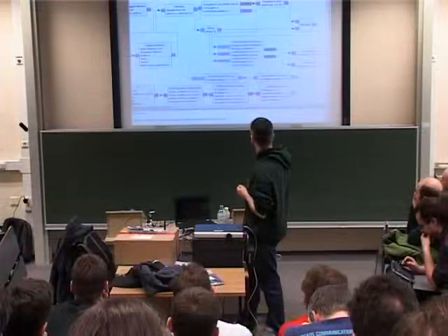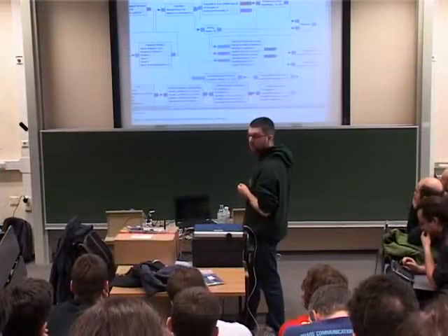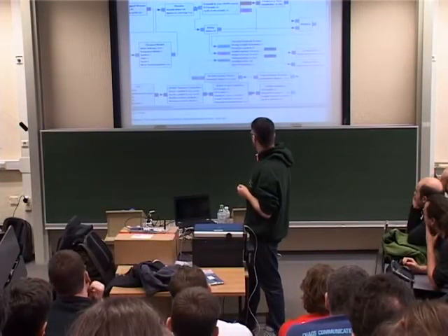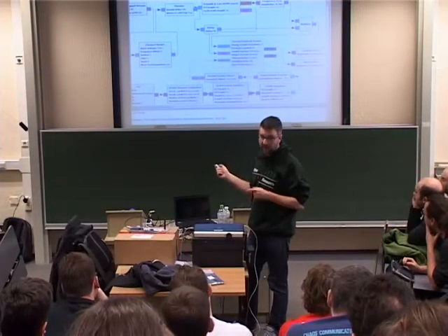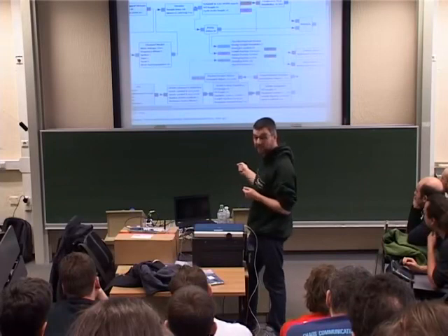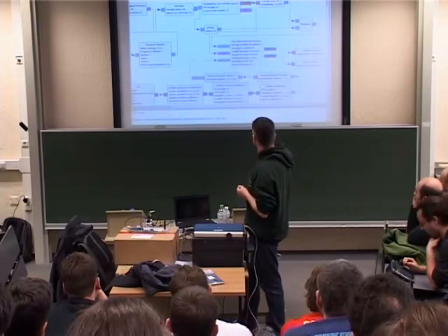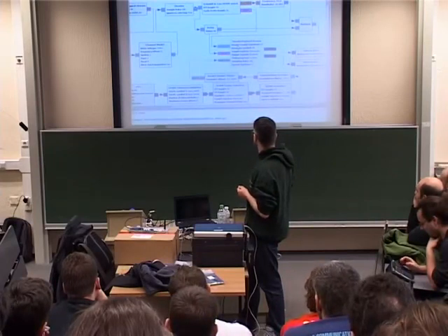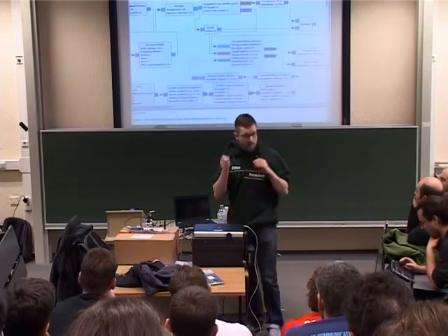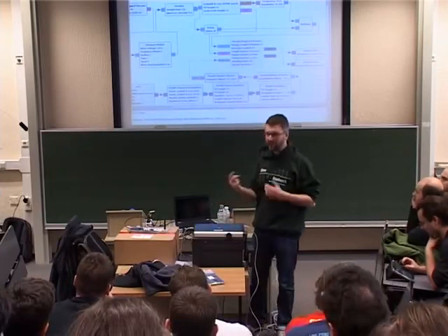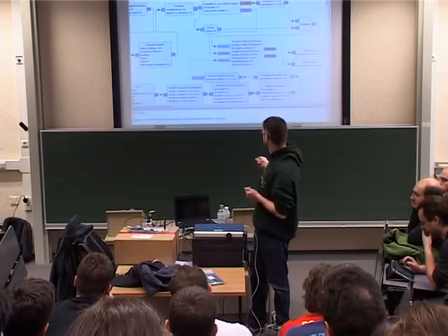Now, this is the part of my flow graph that decodes the header. You can see there's something going on here because suddenly we get these dotted lines, right? This is because what we have here is actually a feedback loop, but not exactly the kind of feedback loop you think of in control engineering. This is asynchronous.